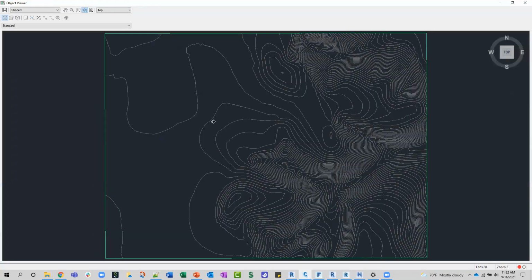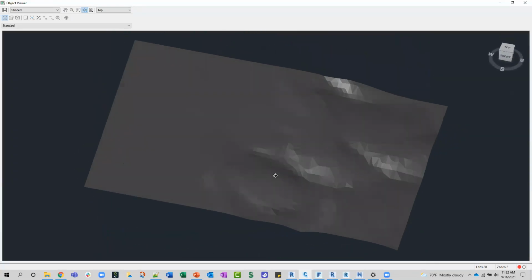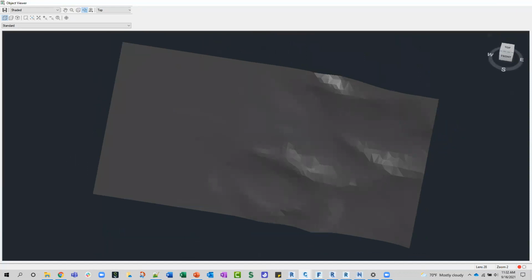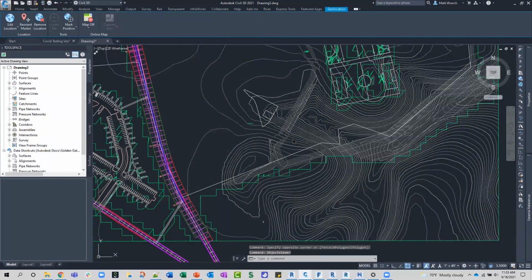I did do a little bit of work on that InfraWorks model beforehand, but here's that existing. And one thing I didn't mention is that terrain that comes across in InfraWorks. That's USGS 10 or 30 meter data, so not super accurate, not super clean. You're not going to get those nice sharp breaks every time you see a retaining wall on a site. It's a lot more of a rolling interpolated terrain, but it's a great start.